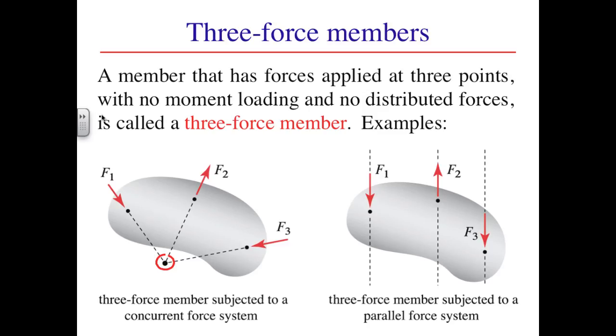Although this may be interesting, I tend not to place nearly as much emphasis on three-force members as I do on two-force members. This is because there generally isn't an efficiency or simplicity associated with identifying a three-force member as such. If we fail to identify a qualified member as a three-force member, we simply apply force and moment equilibrium as we typically do and proceed.